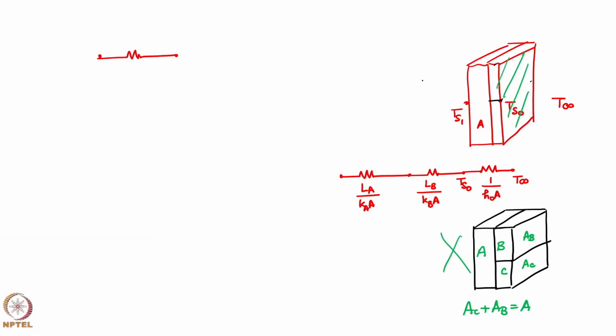On the left hand side you have two paths for heat transfer, Q radiation and Q convection. Now, thankfully, why am I saying thankfully? The air and the walls are both at 400 degrees centigrade, the same number. So, across the same temperature difference, that is 400 minus T si, I am having the heat transfer. Suppose T wall was 500 and T air was 400.